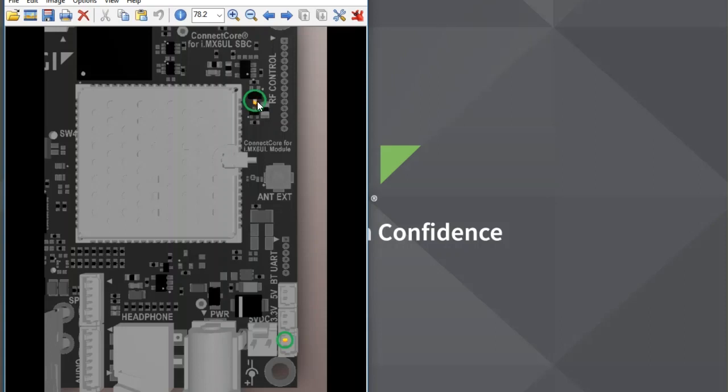Now you have two options. You can connect only one Schottky diode and, in series, your external battery or power supply, which emulates the battery, or if you would like to also reuse the connector which is on the CC6UL SBC Pro, then you need to connect here also the anode of the Schottky diode.